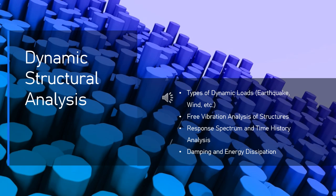9.1. What is free vibration? Free vibration occurs when a structure is displaced from its equilibrium position and then allowed to vibrate without any ongoing external force being applied. After the initial disturbance, the structure will oscillate at its natural frequencies and mode shapes.